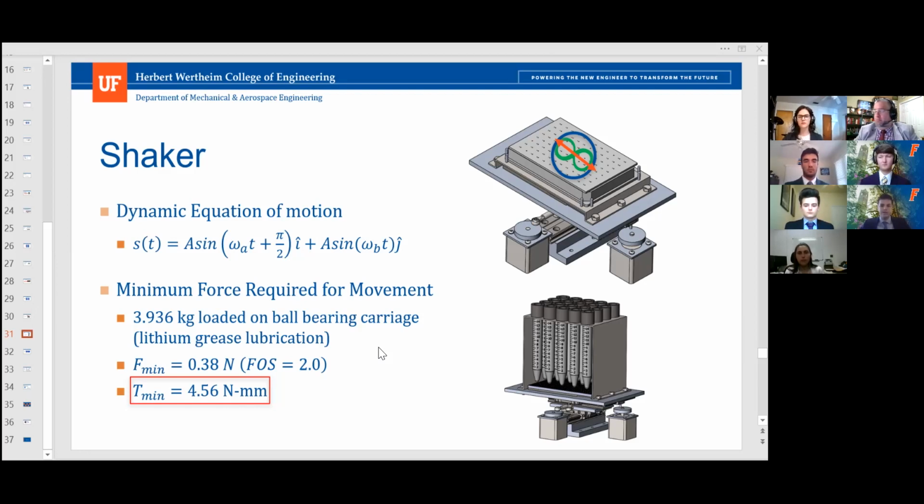The shaker patterns are achieved by the 2 motors. When only one motor is running, a linear pattern is achieved as it moves back and forth across one railway. When both motors are running at the same speed, an orbital pattern is formed. And when one motor is running at twice the speed of the other motor, a double orbital pattern is made.